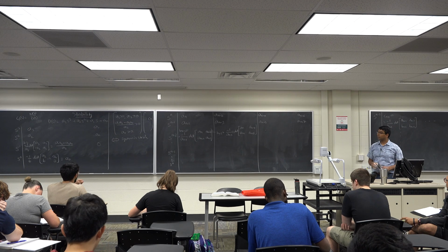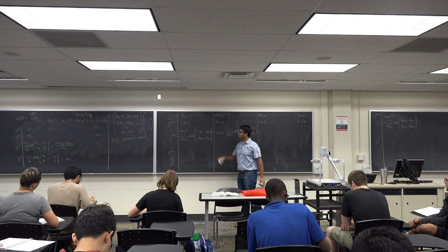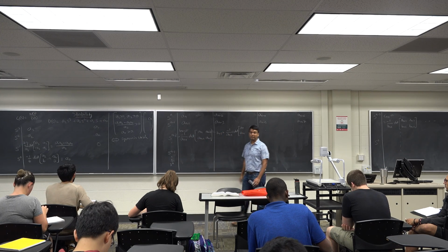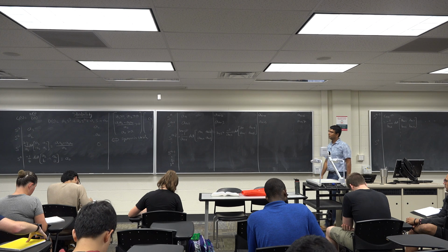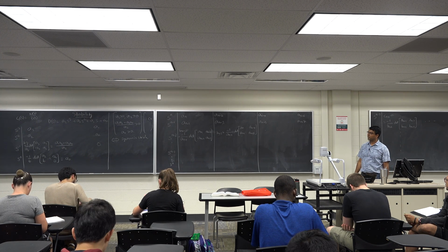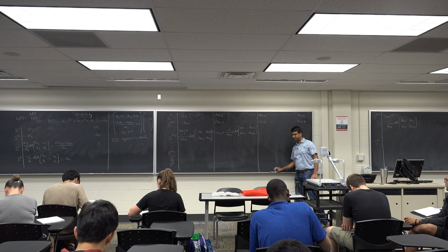All right, so that's what I have for today. We have an easy way to figure out whether a system is stable or not. Just construct the array through simple manipulations, and we can easily conclude whether a system is stable or not. In the next class, we'll talk about some other nuances regarding the Routh array and how to determine relative stability of a system. Thank you.